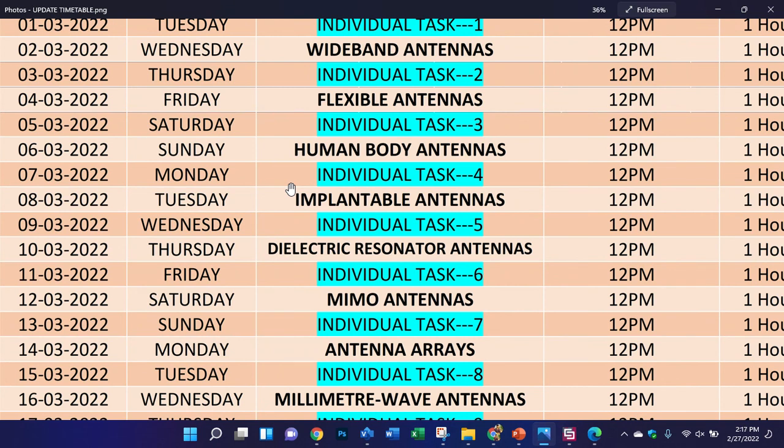They rejected it. Maybe you have done it in a different way, but here the epsilon value, like in human body cases, if you want to insert this antenna you can insert it inside the human body, but in practical cases you cannot. So you need to use a material that has very close properties to the human body, like pork material. Pork material is not available in the Arabian countries, but in European countries it is available. So it is available here, and we tested our antenna inside pork material, and we saw there is not much difference between simulation and measurements, because they are very close to each other. Okay, in terms of epsilon value, relative permittivity. If you know the relative permittivity, then you can claim that you have very close results, and the results are acceptable. Sure. Thank you.